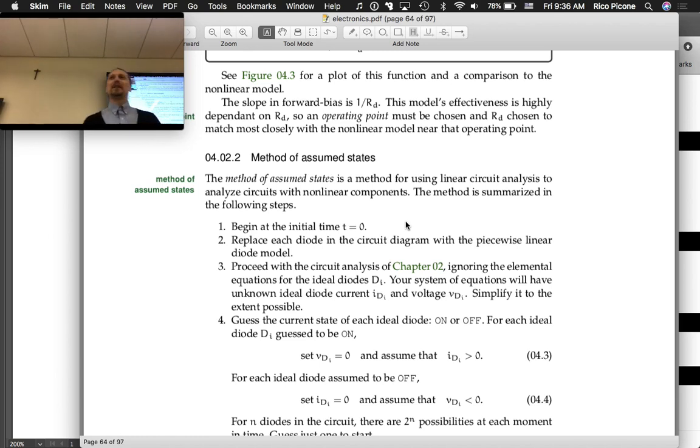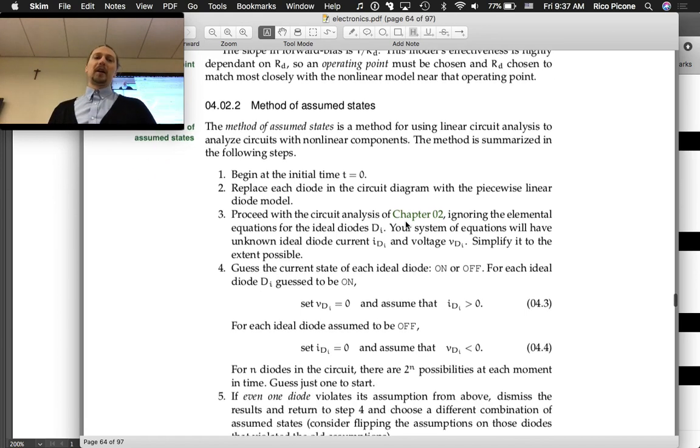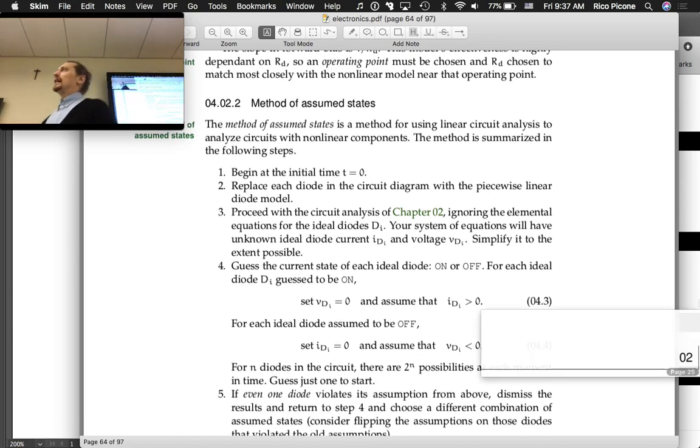So you don't necessarily know which diodes are wrong and which ones are right, but if you can boil down your contradictions to contradictions in the direction current would be flowing or the voltage would be dropping, which is what I recommend in these steps, then you can have a pretty good guess about which ones should be flipped.